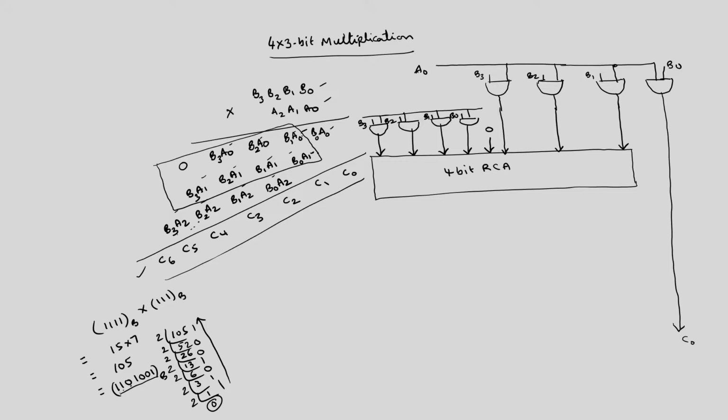Okay. So this addition will be performed by this 4-bit ripple carry adder. So directly the last bit will be your C1 bit. Here the sum bit of this one is the C1 bit, and the carries will be propagated inside this, because this is a ripple carry adder. So the carry from this addition will be propagated to this, and then to this, and so on. That will take place inside, and the remaining 3 bits, totally you will get 5 bits. Okay, you will get the remaining 4 bits along with the carry.